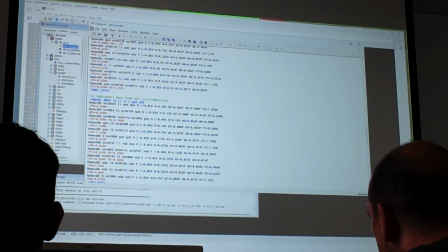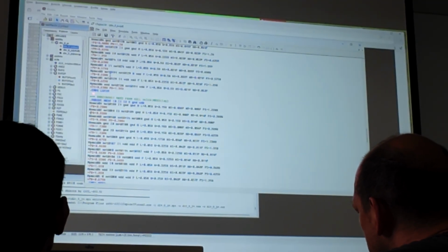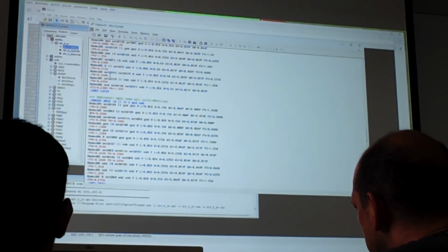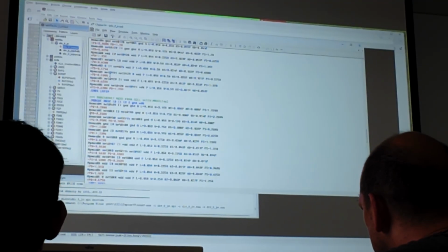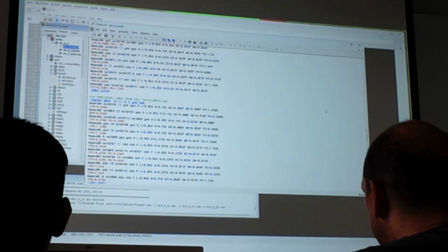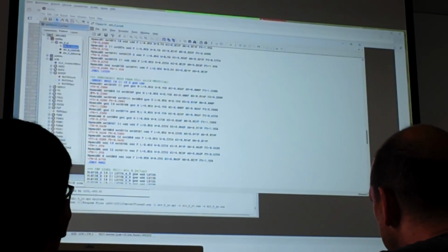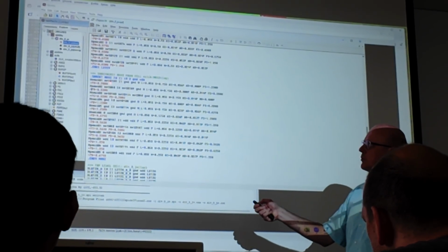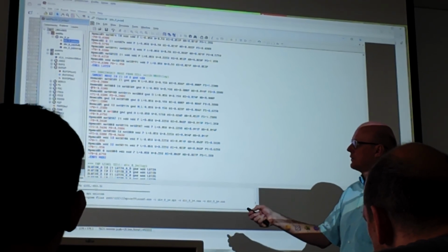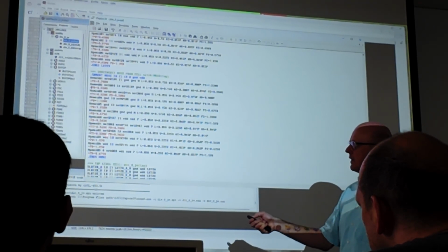And then comes my multiplexer, multiplexer 2, my subcircuit. And for each subcircuit I can count my number of transistors here. So I know my Mux 2 circuit has 1, 2, 3, 4, 5, 6, 7, 8, 9, 10, 11, 12 transistors.